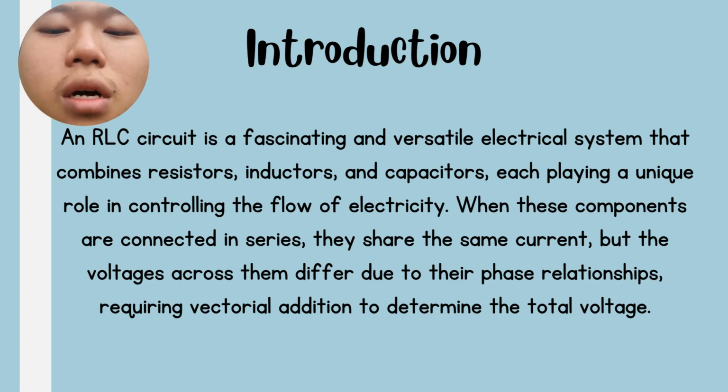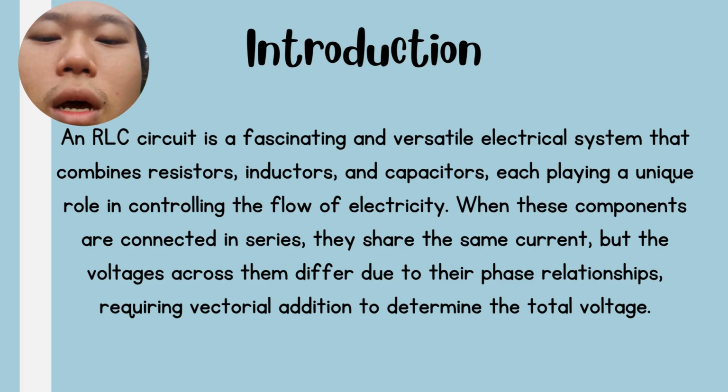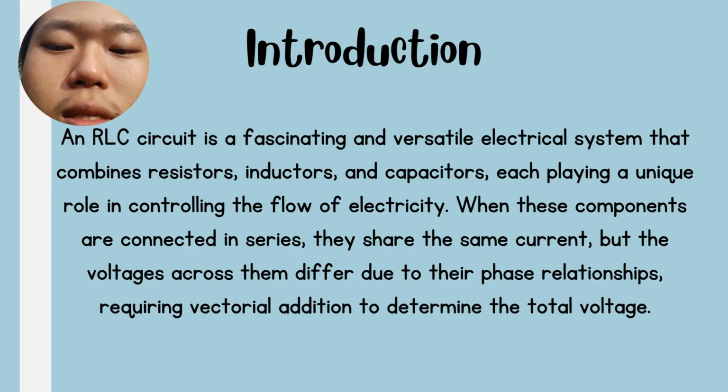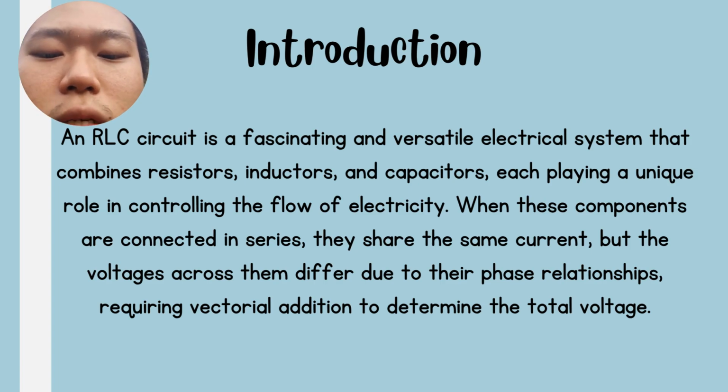So this is the introduction. I will simply introduce the RLC circuit. Overall, an RLC circuit is a circuit that contains a resistor, inductor, and capacitor. As you can see here, it's a very fascinating and versatile electrical system. When these components are connected in series, they share the same current, but the voltage across them is different because of their phase relationship. So they will need additional vectorial addition to determine the total voltage.